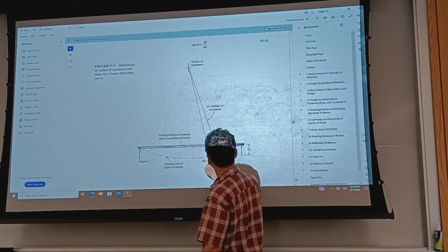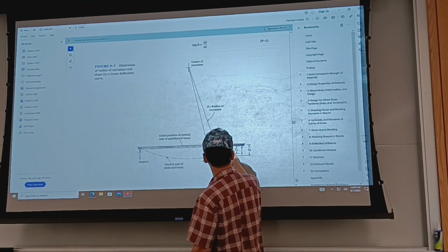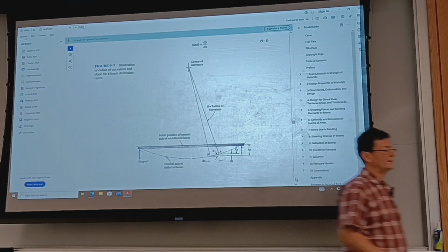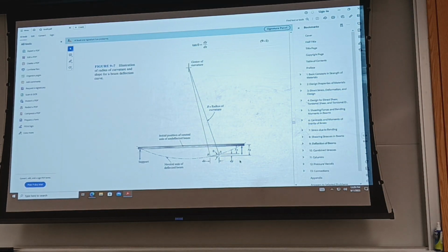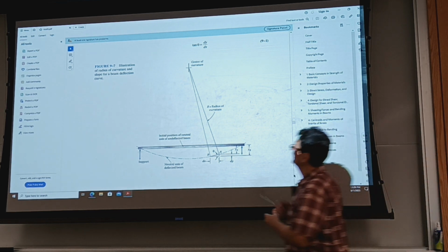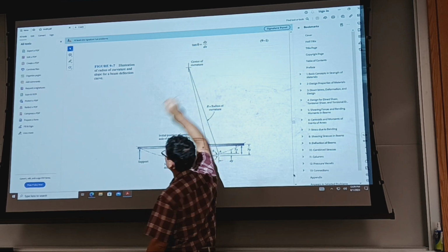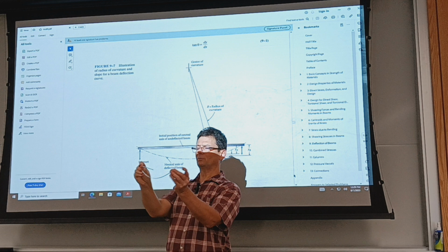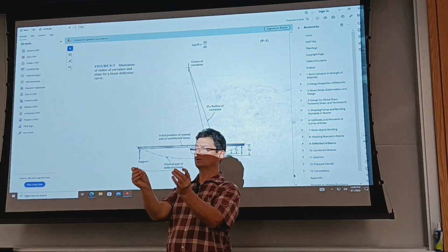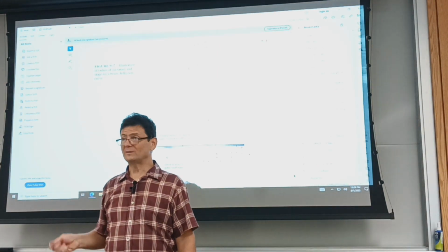Again, we move along the beam. We have infinitesimal variation in x and y. There's a way you can relate the equation of y of x to the radius of curvature. You saw this in other classes. We keep on saying slope theta, but for small angles, which is our case, since beams don't deflect dramatically in our analysis, just slightly, you can approximate the tangent of the angle with the angle in radians.